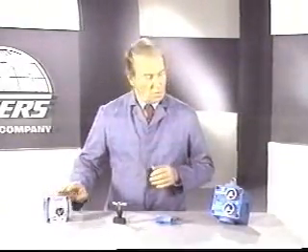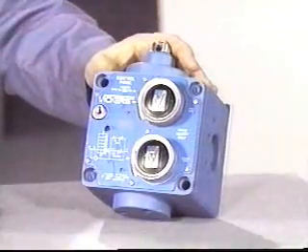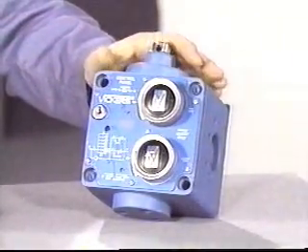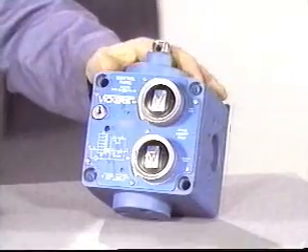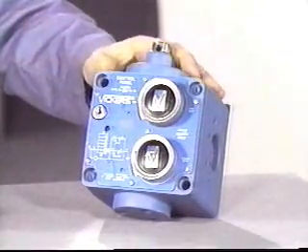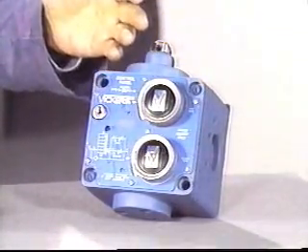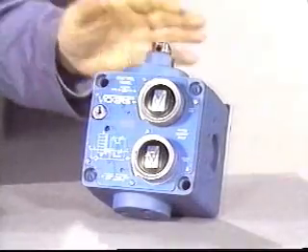Over here, we have a feed control panel, which in effect is 2 flow controls. This package allows the cylinder to have a rapid advance and course and fine feed cycles. It, too, is installed in the circuit by means of a subplate. No oil lines are connected directly to the valve body.